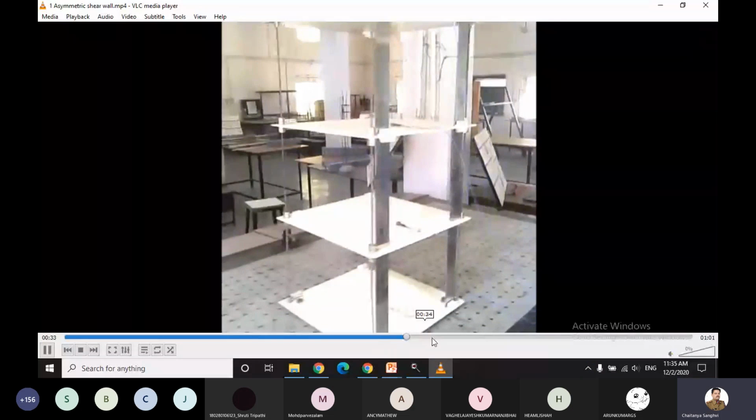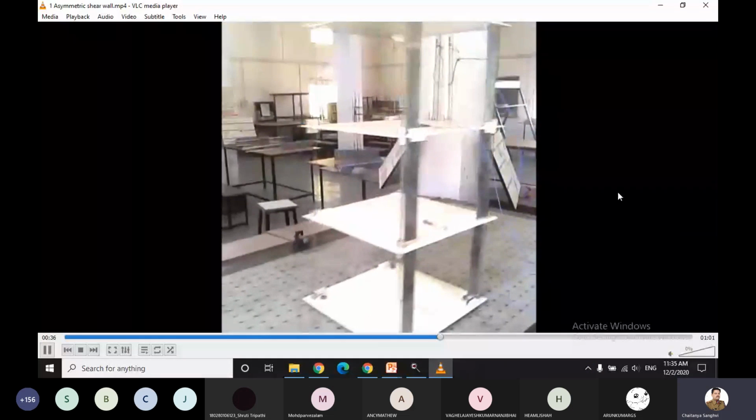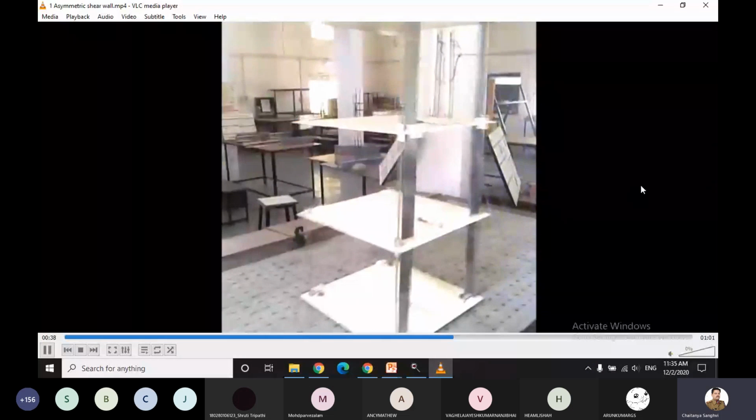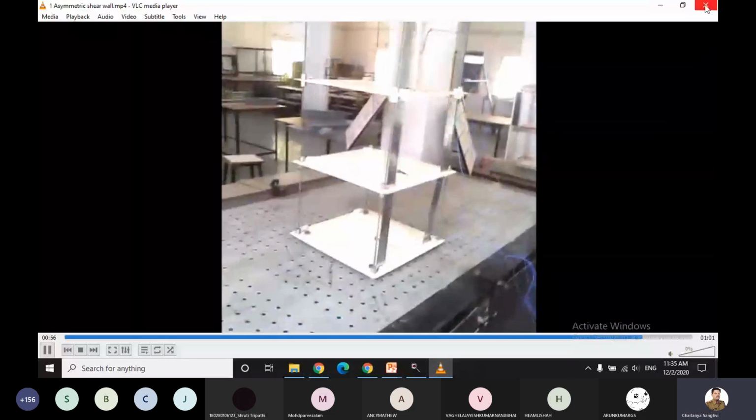This is very important, right? Look at the torsion. So you see, during an earthquake, we are not able to handle earthquake force properly, and therefore I request you, don't do it. Make your structure symmetrical, and then the torsion can be avoided. Otherwise, earthquake force plus torsion both will come, then it will make your life miserable, I tell you. Right? Okay.